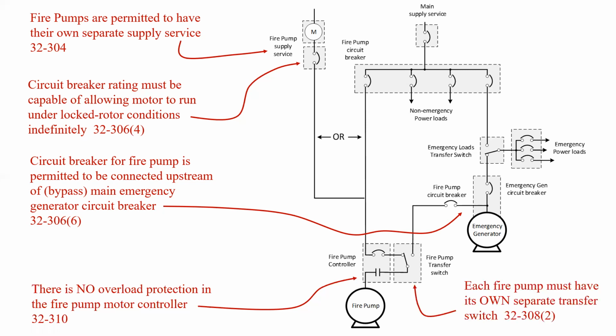Finally, each fire pump must have its own separate transfer switch. If we have 5 fire pumps, we have 5 transfer switches. And this is again redundancy to ensure that if one transfer switch were to fail, the remaining pumps would still function.